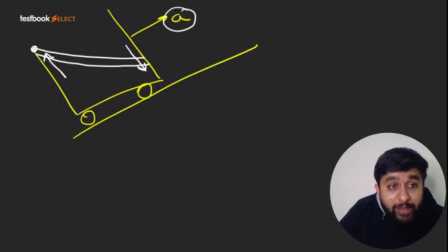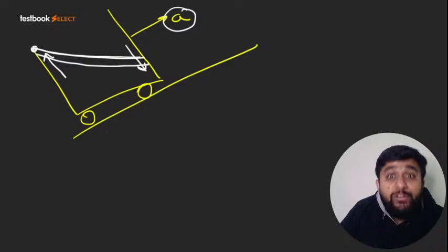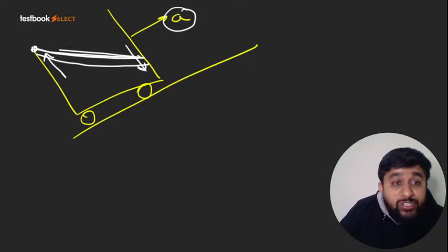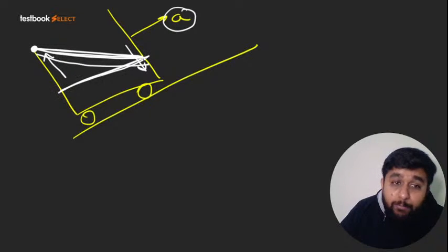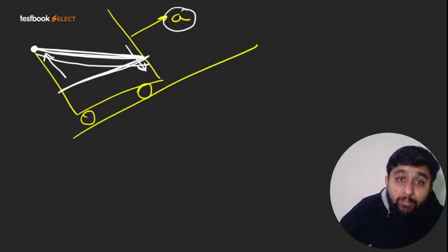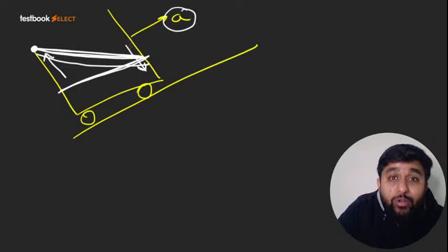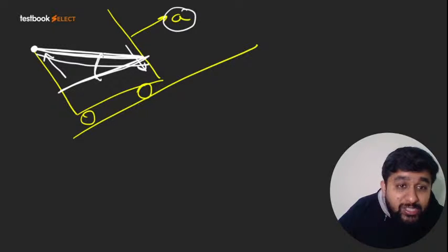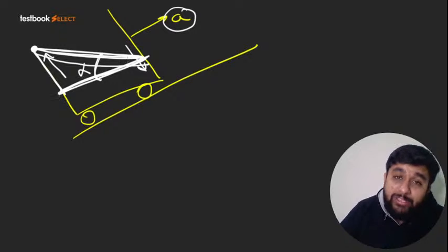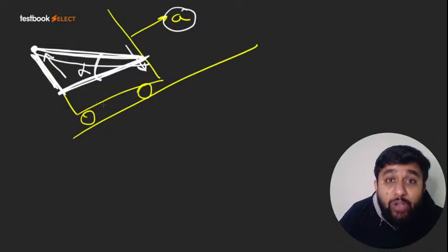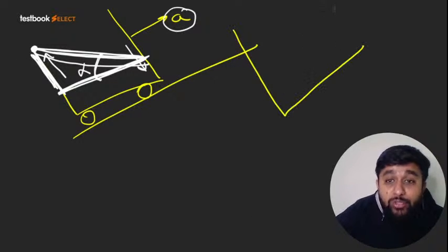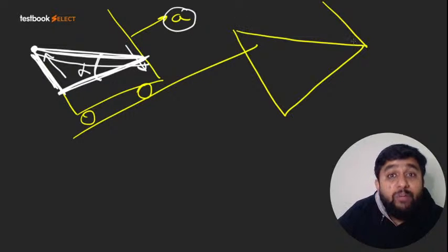So what I did, this I am sure water is just about to spill out. It is given in the question. Now I found out the slope of top surface of water. This means I can divide the total shape in a rectangle plus triangle. But initial volume of water is equal to final volume of water. And also this tan alpha is equal to height of triangle by the base. So first of all I got that the height of triangle is equal to 20 centimeter, same as that of container. So I found out this will be the final shape of water in the container.